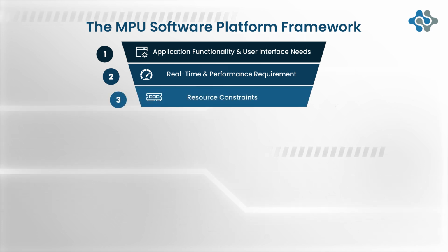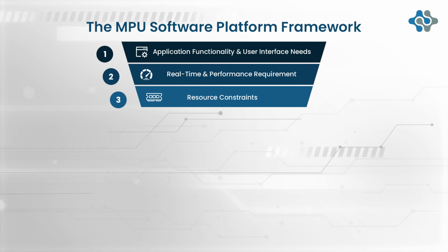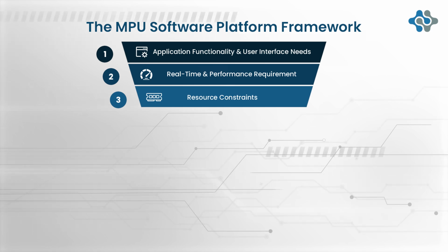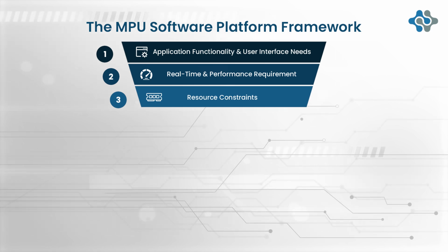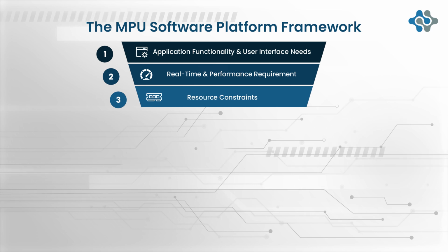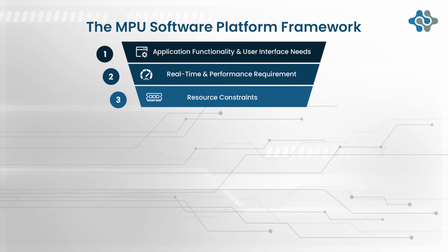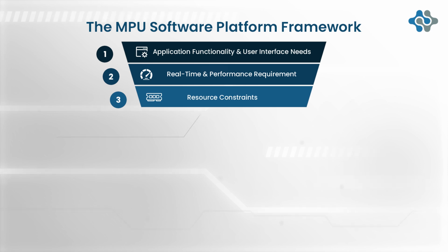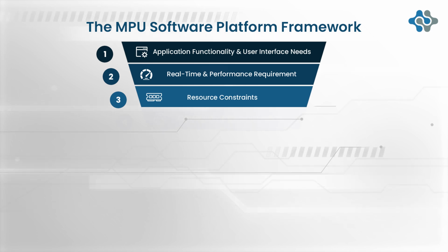Criterion 3. Resource constraints. While MPUs have more resources than MCUs, they aren't infinite. Android requires significantly more RAM, flash, and GPU power than a minimal Linux system or an RTOS. What are your hardware limits, and how do you match the OS needs?